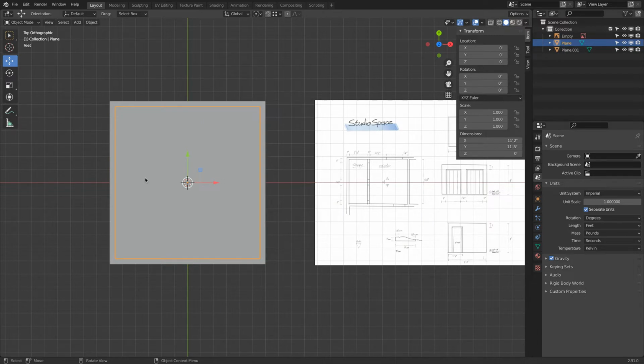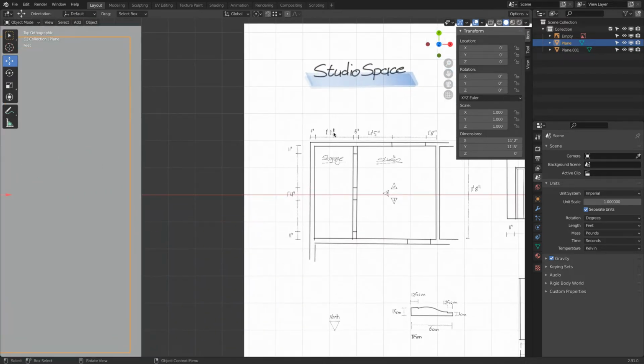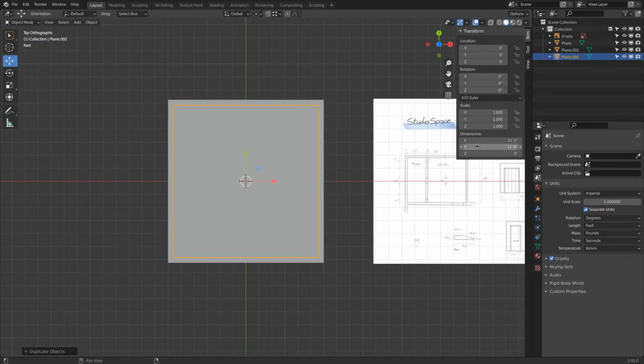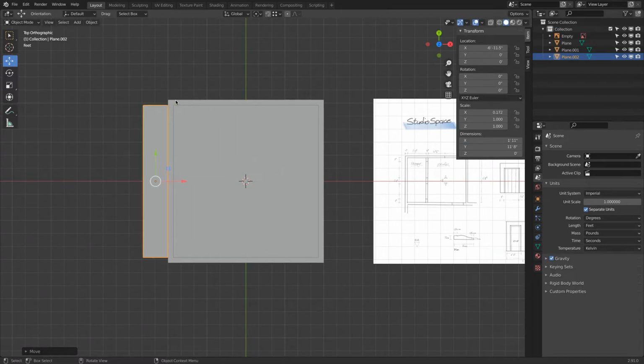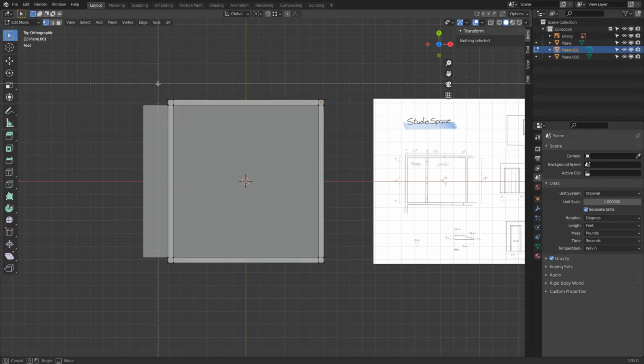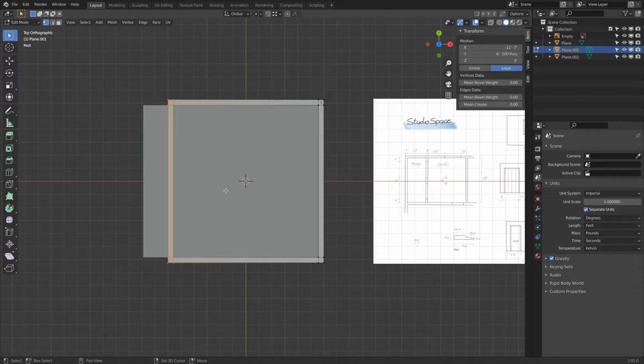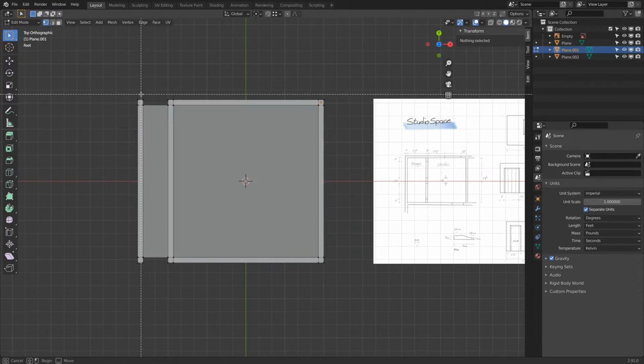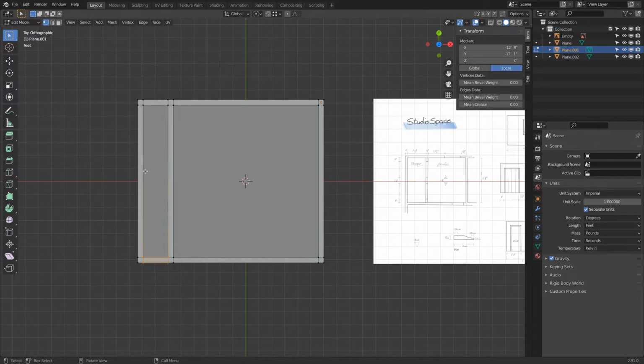Okay, and we can select this rectangle in object mode. This is 1 foot and 11 inches, so Shift D and escape. Height is correct, just X 1 foot 11 inches. There we are. I can bring this over, bring this back to snap to there, select our wall, go into edit mode, AA, and we'll select all this. Shift D and press X, G and X, and then we snap it back to there, AA, B, F, AA, B, and F. Okay, so you saw this actually super easy. We simply place corner rectangles onto room, and then we can very quickly connect the shapes for the walls.